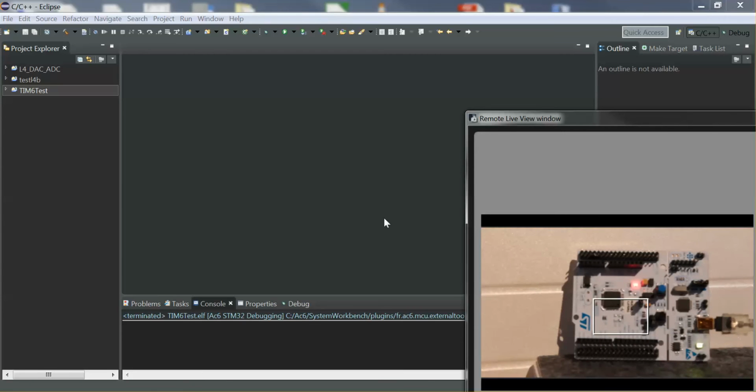So if your board breaks out, normally you also have a breakout for the ST-Link, but if not, then you just use normal jumper cables and you connect to the pins that are broken out on your board, and you should be all set. The advantage is that obviously it is much cheaper. Maybe it's not that powerful in terms of speed of uploading data, but for most applications, I think you would not notice the difference.